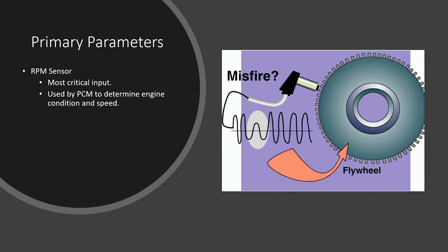Going through with misfires, this is another thing I wanted to take into account here and share with everybody. The way the misfire monitor works is we're measuring how fast that crankshaft's spinning. If there's a misfire that occurs for any reason, say a spark plug's bad, make up whatever reason you want, it's going to slow that crankshaft down because we don't have the combustion forcing that piston back down inside there. So it's going to momentarily slow that crankshaft down. It always uses a backup. In the previous YouTube video, I said always back up your suspicions.